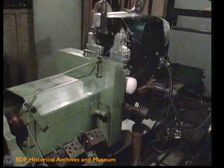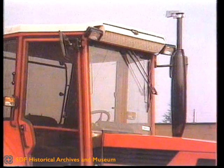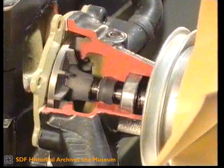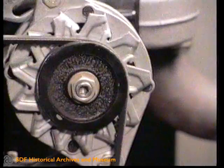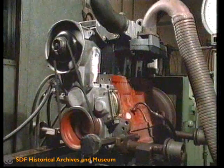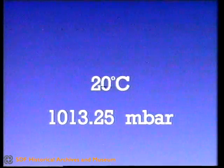This is a test of the engine with all the standard accessories necessary for its normal use: air filter, discharge gas exhaust system, water pump for water-cooled engines, cooling fan and alternator not under load. By means of corrective formulae, the measurements are always referred to temperature and ambient pressure conditions of 20 degrees centigrade and 1013.25 millibars respectively, for the purposes of being able to compare test results conducted in different places and under different meteorological conditions.